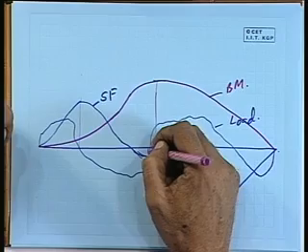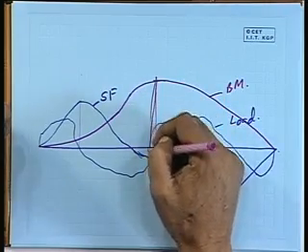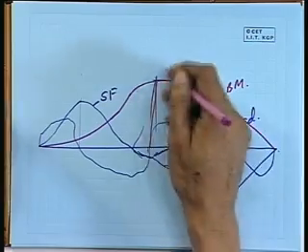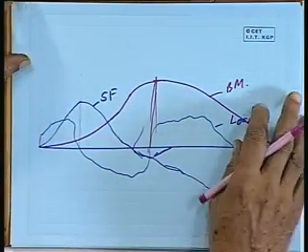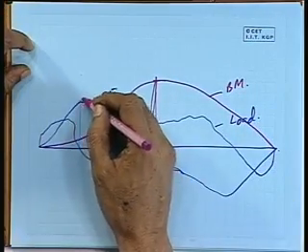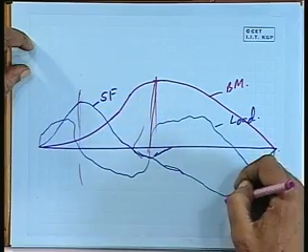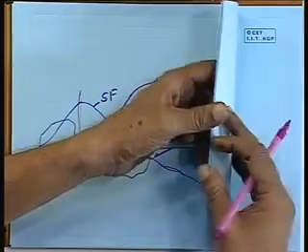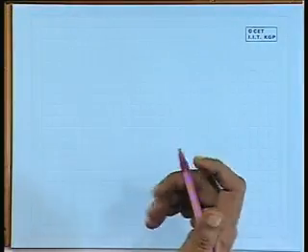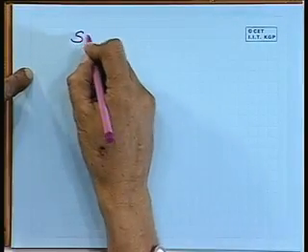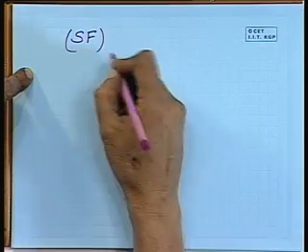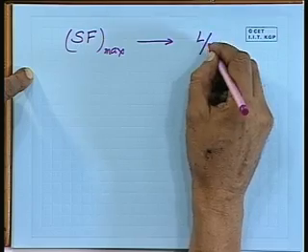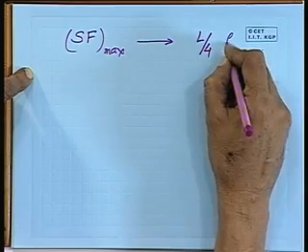Okay. So, once you have this type of curve, we see that bending moment will be maximum somewhere here, where the shear force is 0. Somewhere around the midship region it will be maximum. Shear force will be maximum somewhere here and another value somewhere here. So, what we can say is that the shear force maximum value is somewhere at around L/4 from ends.